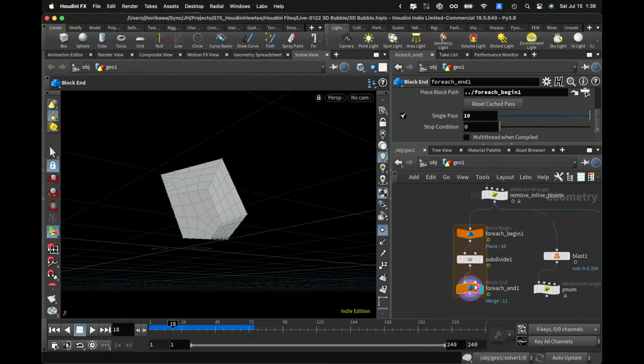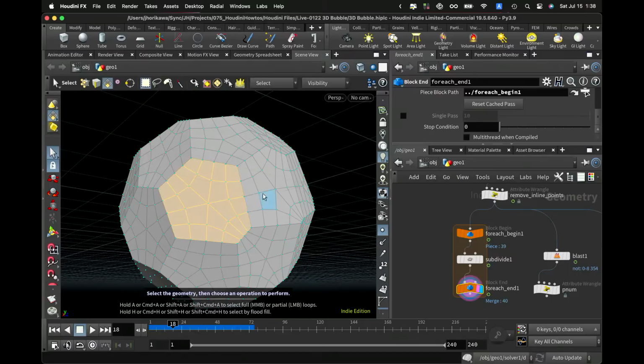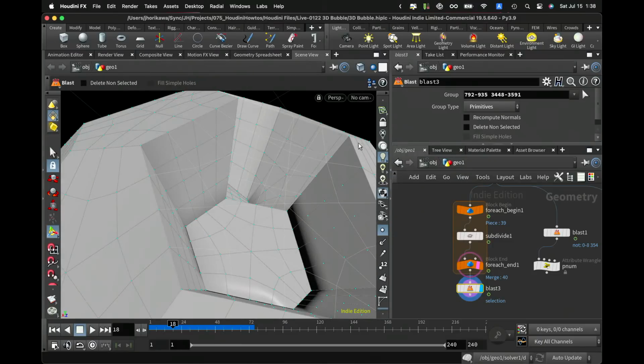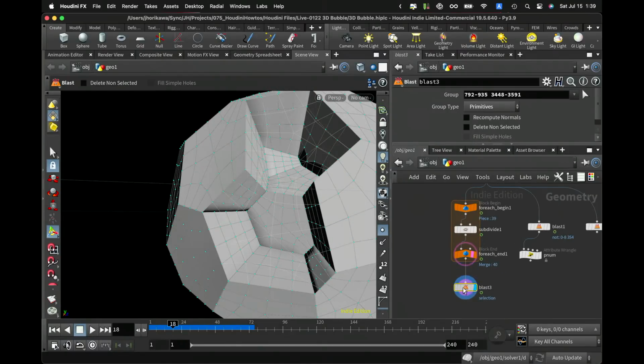So the good thing is that even if you pick this cell or this cell or this cell, the neighboring surface always shares the same point position and same point number, which will make it easy to pair each point to have the average point positions later. Okay, so that's the reason why I'm using subdivide.